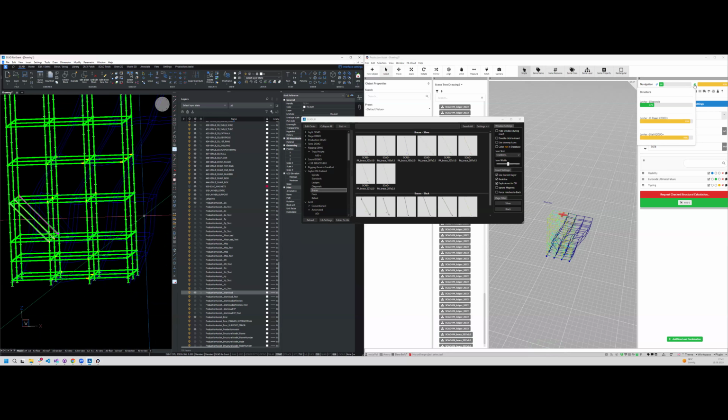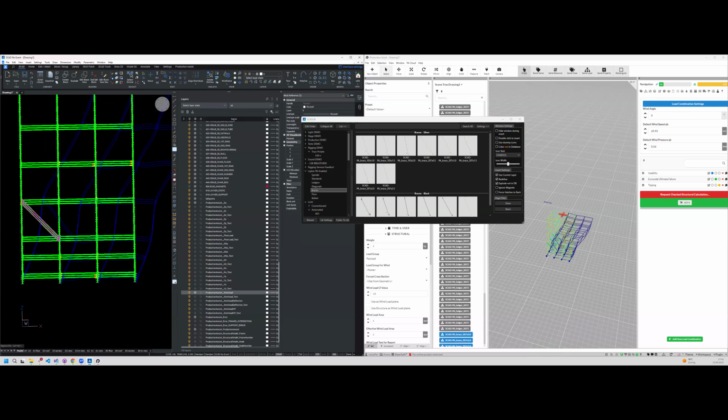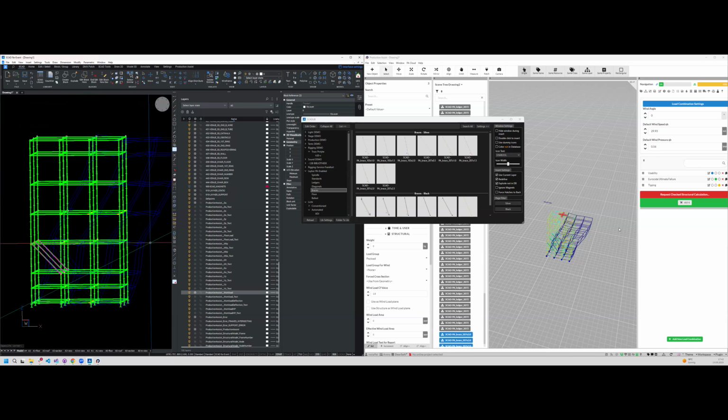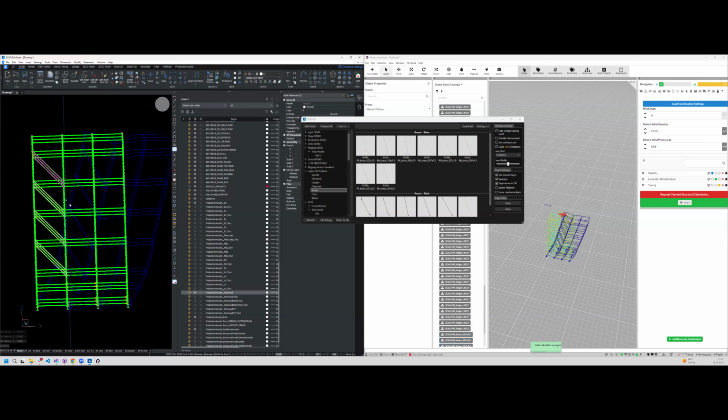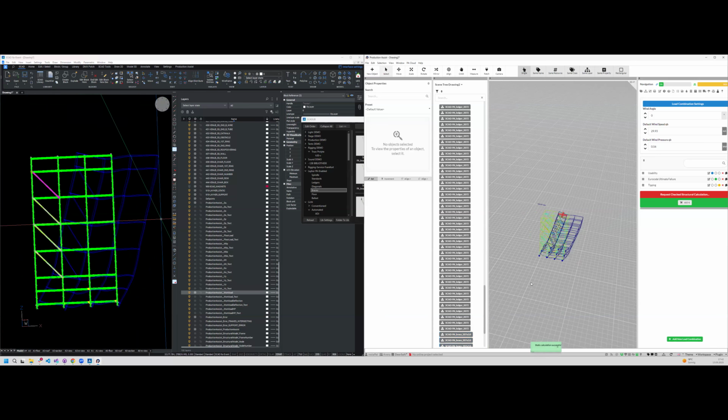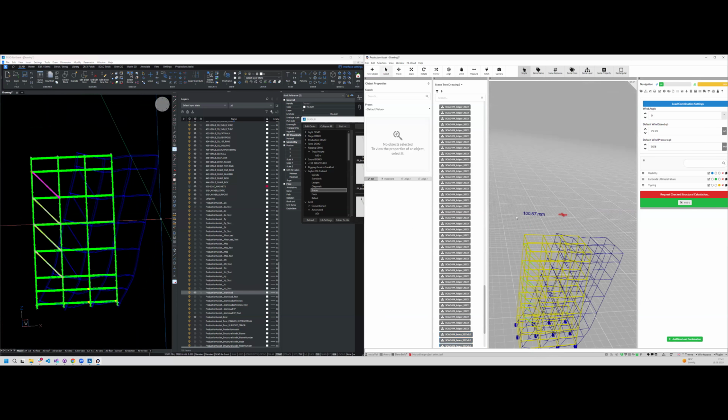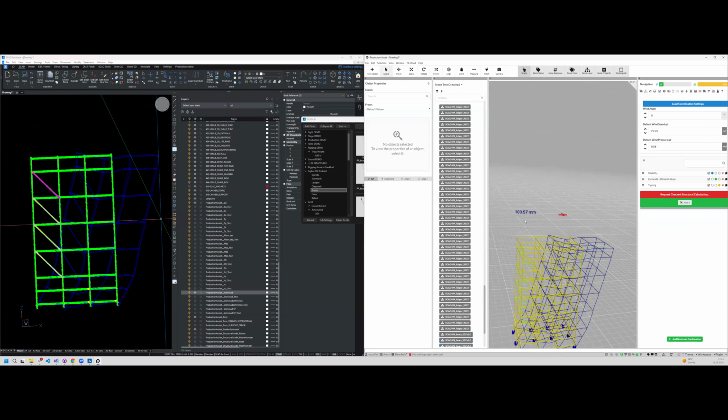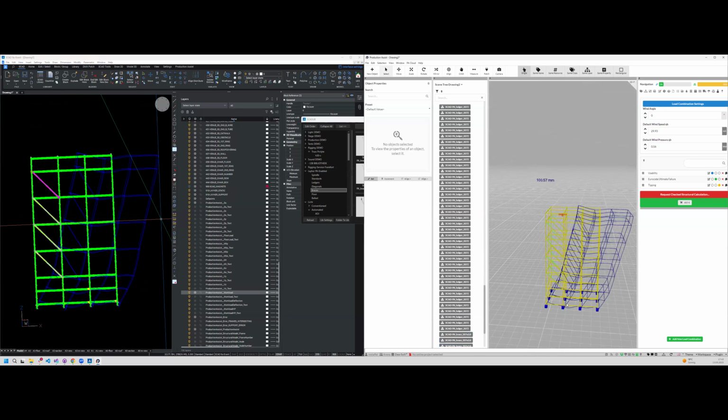So you see that's the advantage of direct calculation with this, to see what kind of changes you need to do in order to calculate this. So the next step that I'm doing, you see it's good enough, but it's still deflecting a lot. So I'm copying this, do CZ, type in 2000 for the copying, enter, enter, enter. And then I have this in here, and I see the diagonals also bring down the actual deflection. So you now have about 10 centimeters deflection in here.